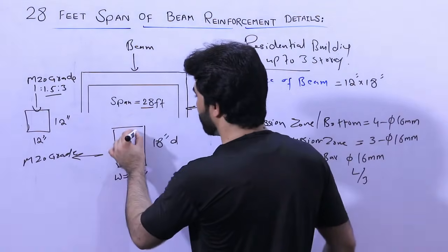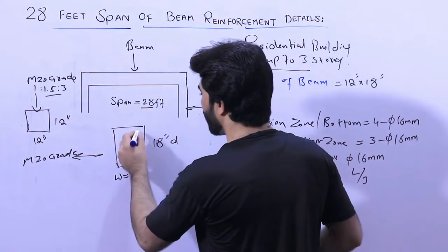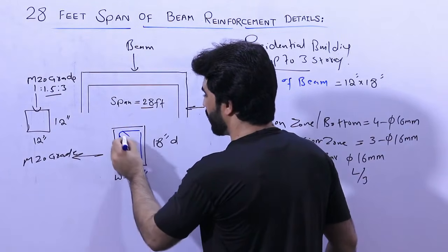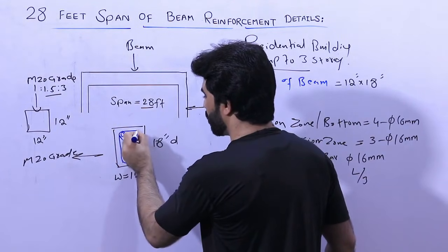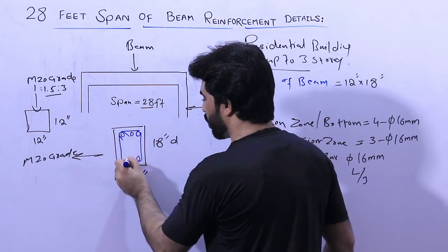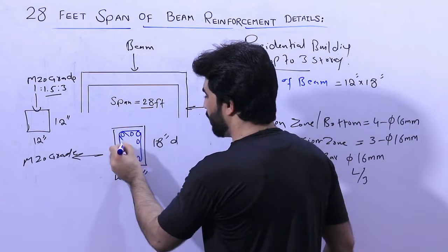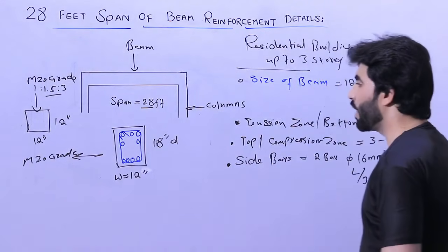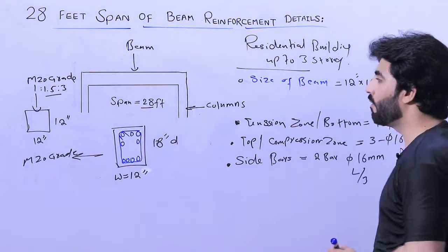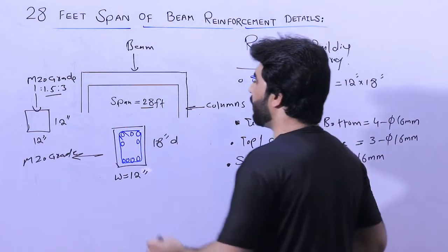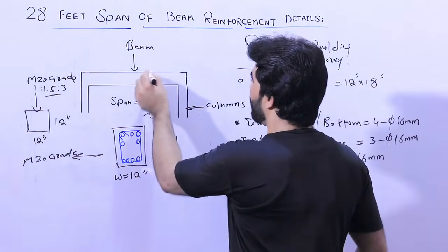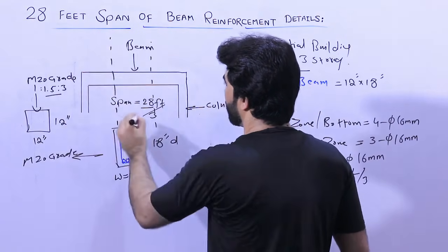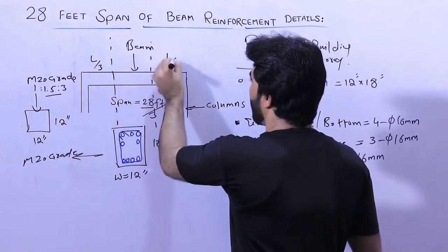If you see guys, this is stirrup, and this beam, this is stirrup, and these are hooks. 1 bar, 2, 3 and 4 at the bottom. 2 are side bars at the top portion, where we provided at the distance of L by 3. What is L by 3? Means span divided by 3. Let me make a section. This is L by 3, L divided by 3.